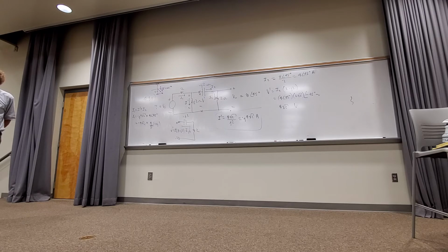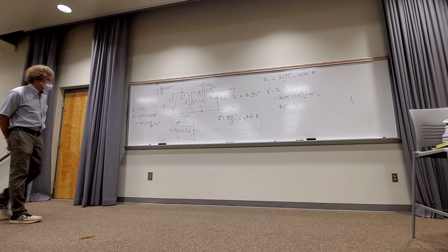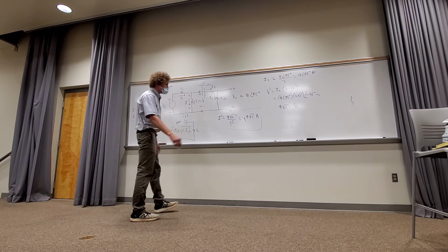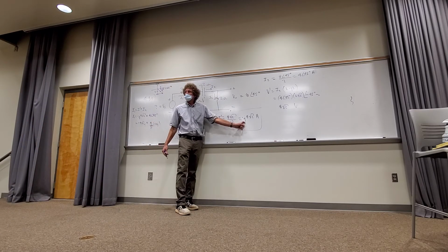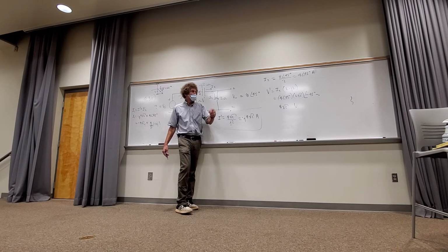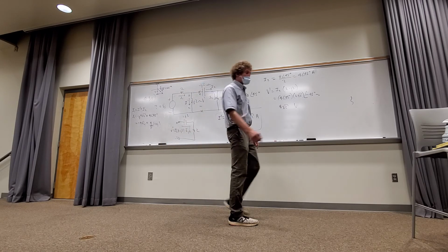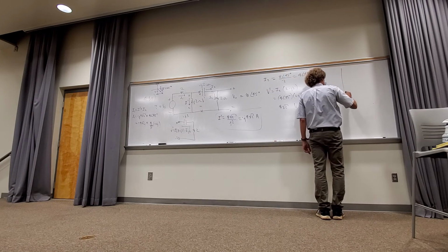Yes? Would the negative j4 root 2 be 4 root 2 at negative 90 degrees? Yeah, she sees a minus j times a constant, right? Minus j is 1 at an angle of minus 90 degrees. The way you always get this stuff, think of the complex plane.